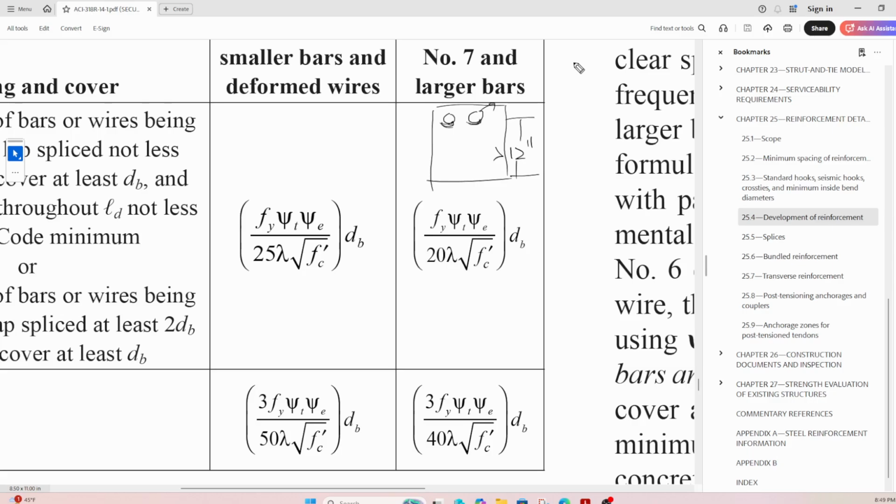Again, it is similar to a person holding a reinforcement bar with his wrist. If you have some moisture between your fingers, and someone is trying to pull the bar away from your hand, then you need more grip, like wanting to have a wider wrist. A friend who has a wider wrist than you can hold the bar for a little longer, right? So the width of the wrist is like the development length here. These are funny analogies, but I'm just trying to simplify all this.